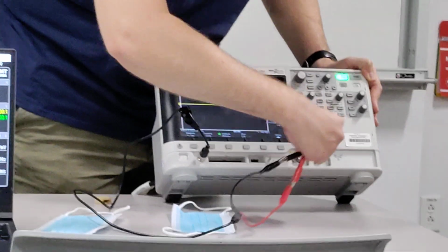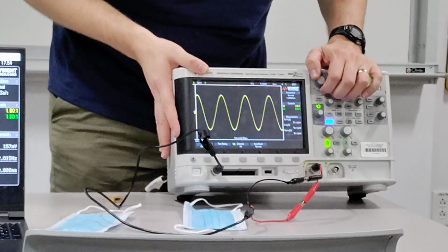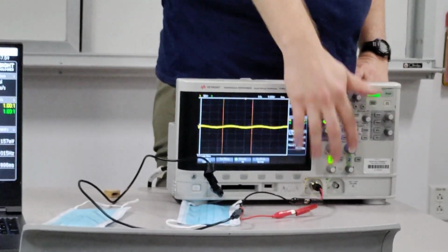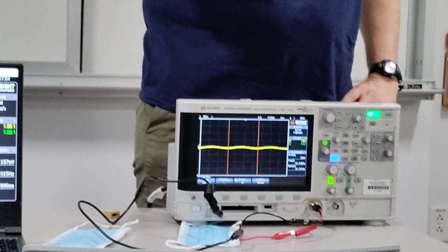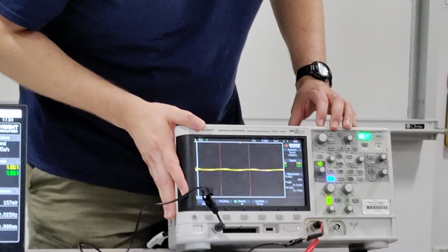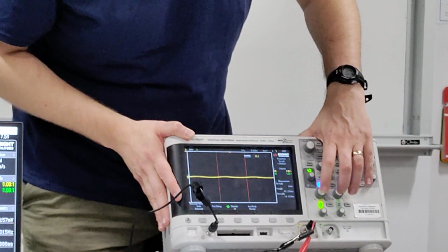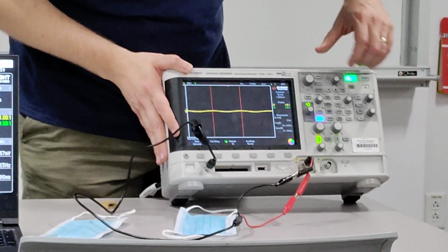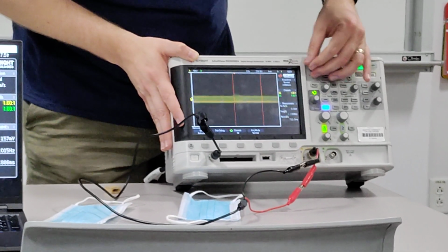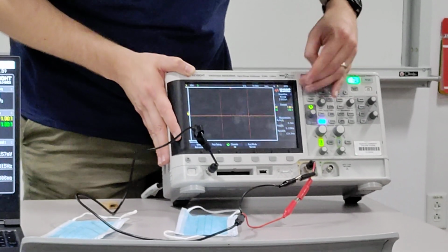It also might have just auto scaled to something horrendous, which, oh, there we go. Which is why I say you're going to need to learn how to use a horizontal, vertical, offset measurement, all that stuff you need to be able to do yourself in case the auto scale just throws you away. One thing I haven't mentioned, basically all these buttons, you can press them, which is quite handy. So if I go back to auto scale, I have an ugly signal, which is just gone. It's gone forever, apparently.